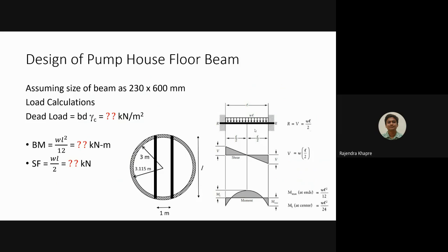Now this time I am assuming the depth of the beam as 600 mm. I am slightly going on the higher side, you can provide even less also, but later on we'll have to check whether it is sustaining or not. Now we have to see the load calculation.